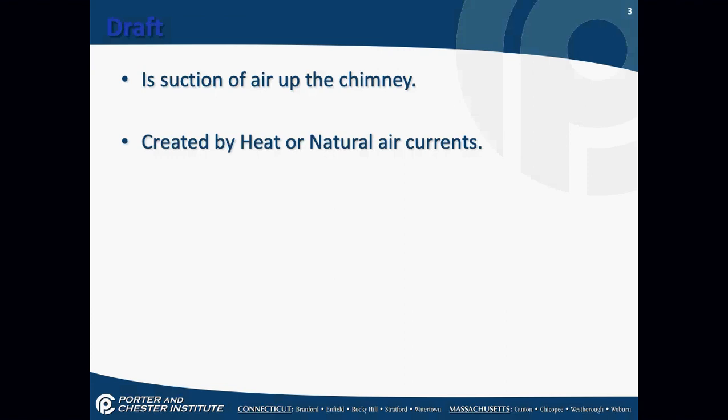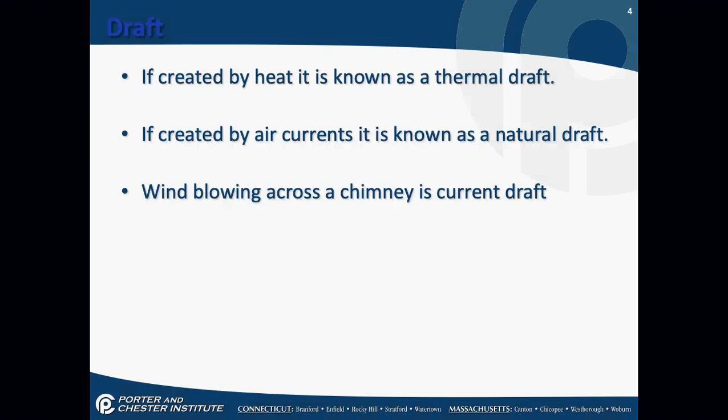Okay, the draft, the word draft, is the suction of air up a chimney. Hot air rises, cold air falls. Draft is created by heat or natural air currents. The hotter the chimney gets, the more draft I have. The cold chimney, when you first start the burner, doesn't do well with draft.